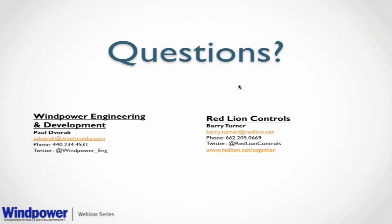Okay, very good. George asks another question that is on my mind too, which is what type of fiber connector do you see the industry standardizing on? If you're looking at 100 meg, it's going to be ST. That's what I see for the most part, ST type connector. And ST is probably my favorite because, like I said, it's got that stab and twist, or it's got a BNC type connector. You can push it in and twist it, and it's locked in place. The SC is a plastic, and it snaps in there. It's still great, but if there's any vibration, it wouldn't be quite as good as an ST would be.